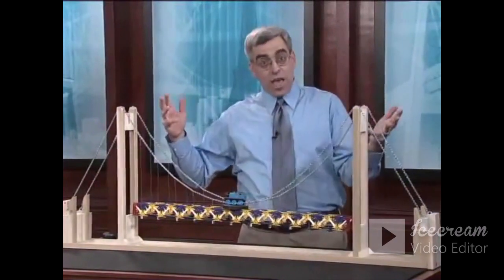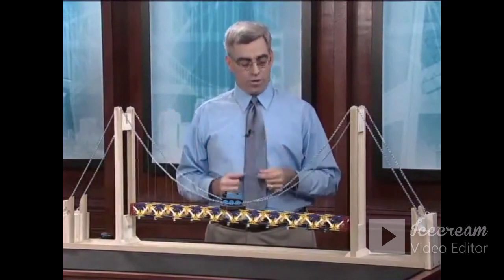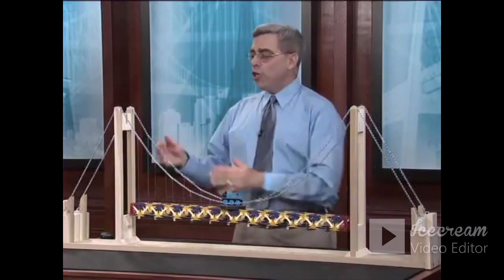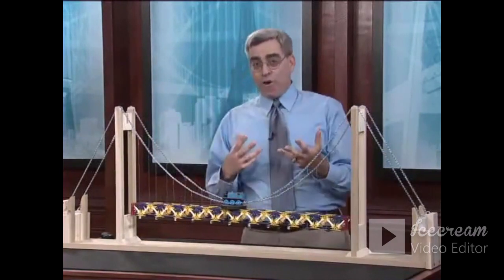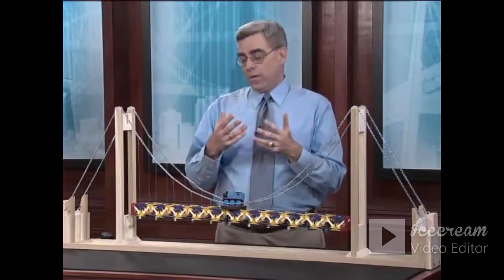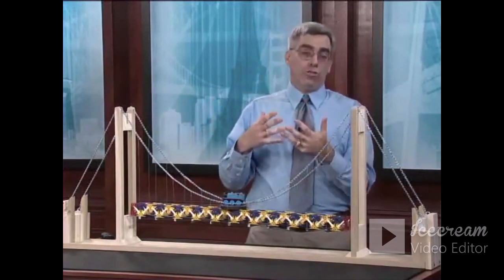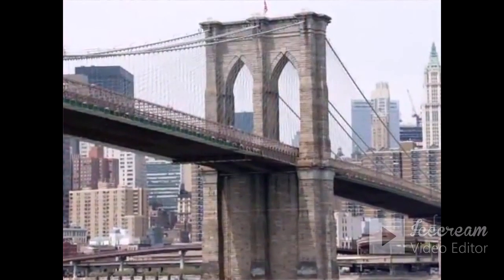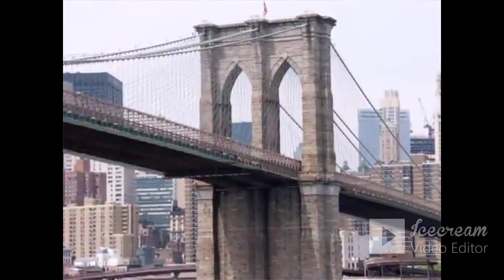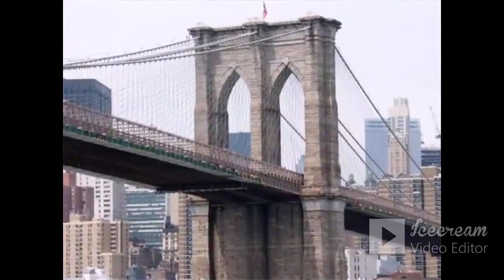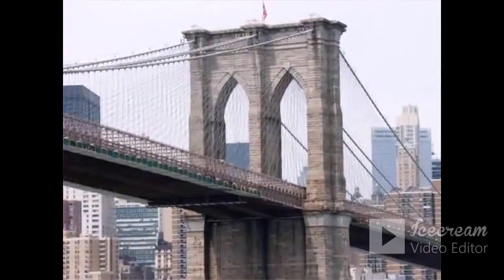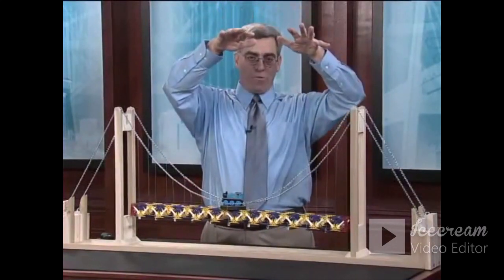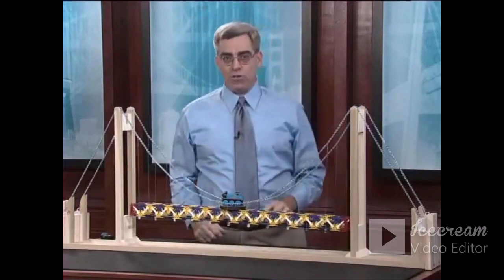The cables we've already discussed, and they are cable-type structural elements, again, one of the 6. The cables transmit their loads into the towers, and because the towers transmit load in compression, they really function fundamentally as columns. Even though we think of them as towers, structurally speaking, they are in fact columns. And while my model doesn't show it, when you look at the image of the Brooklyn Bridge and its towers, you can see that the towers themselves are pierced by a series of arches which allow the roadway to pass through the bridge. And those arches are important structural elements as well because they create an opening and channel that tremendous amount of compressive load coming down through the towers around the openings and down to the structural foundations.